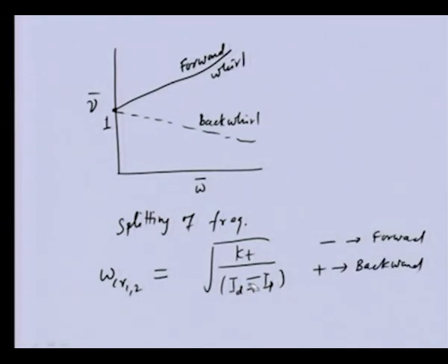because when the denominator is minus, obviously this quantity will be smaller and we will get the higher critical speed, which will correspond to the forward whirl natural frequency. And when it is positive, we will get a denominator higher as compared to the previous one. So, we will get a lesser critical speed, which will correspond to the backward whirl critical speed.